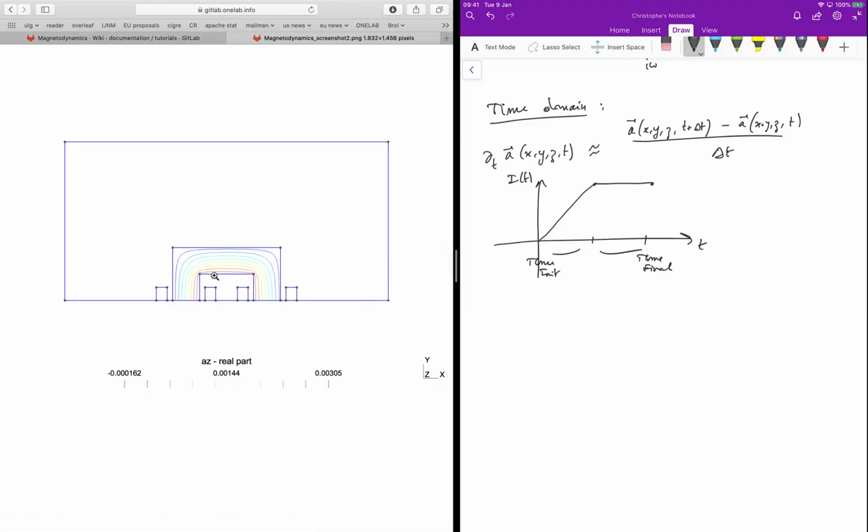It's again a 2D model, quite simple geometrically. So in practice, if you do an actual design, it's going to be a bit more complicated, but this is already quite nice because it has all the main ingredients that you need to do transformer modeling. So we exploit symmetry again, right? You have a symmetry plane or curve over here. So you can imagine that you have the same geometry mirrored for the negative values of y.